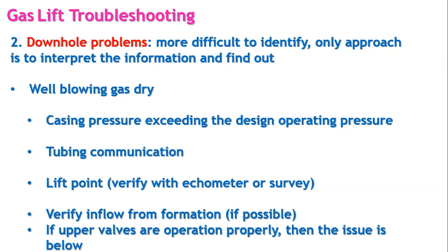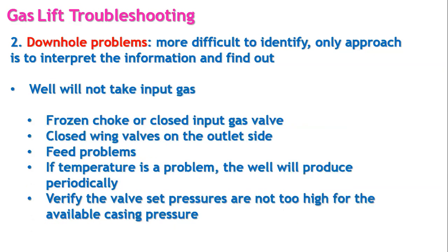This is causing pressure exceeding the design operating pressure, tubing communication, the lifting point, and we have to, in this case, verify the inflow from the formation if there is some setting or increase in the gas from the reservoir that initially we didn't consider, or upper valves are not operating properly. So in this case, the issue is below those valves.